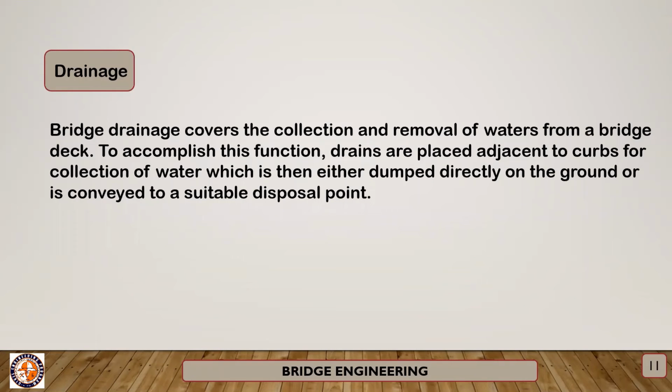Next, the drainage. Bridge drainage covers the collection and removal of waters from a bridge deck. To accomplish this function, drains are placed adjacent to curbs for collection of water, which is then either dumped directly on the ground or is conveyed to a suitable disposal point.